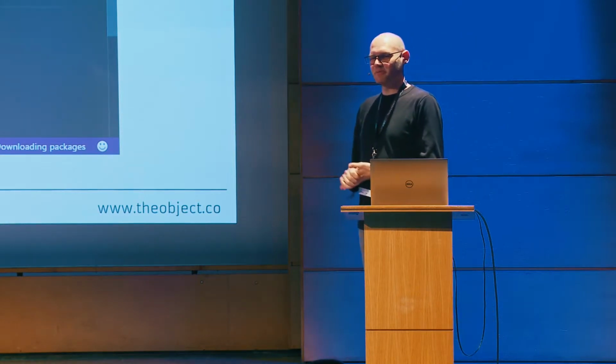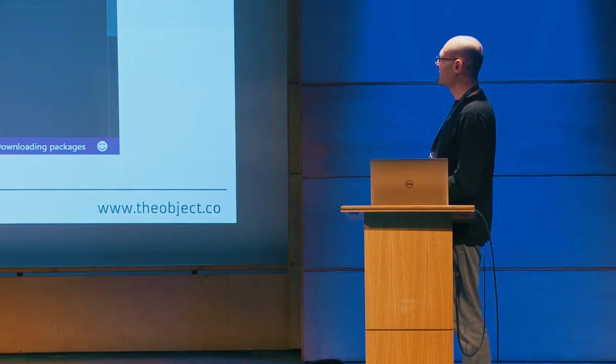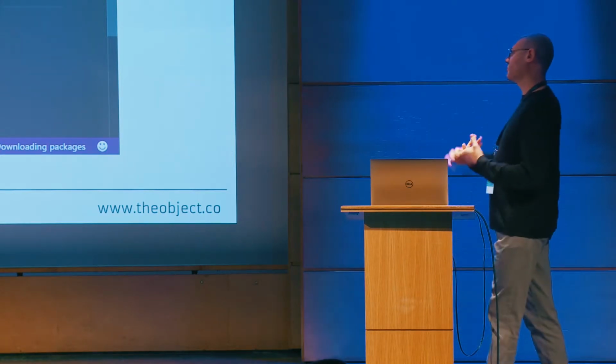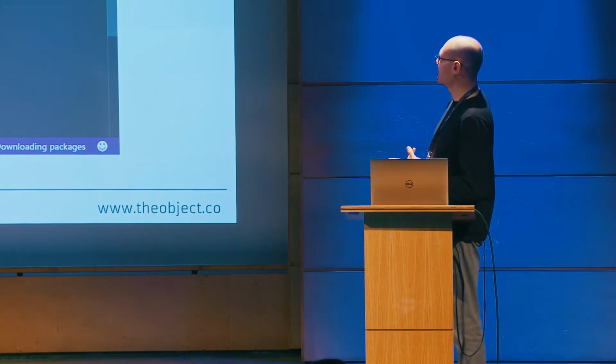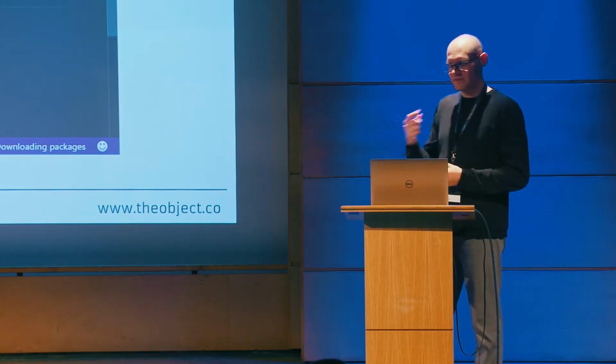To describe the box, it's actually Rhino Common, a geometrical library used in Rhinoceros. If we want to create a box using this library, we have to create a point, and then a plane based on this point, and then using this plane and some dimensions, we can finally create a box.